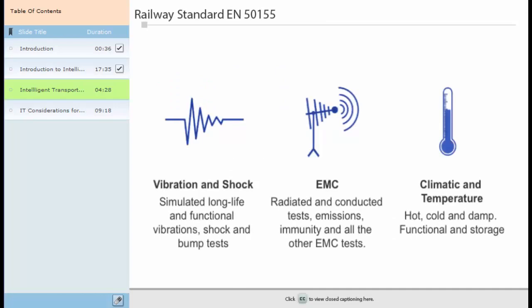The railway standard EN 50155 applies to electronic control, regulation and protection devices on board rail vehicles that are associated with the vehicle's accumulator battery, a low voltage power source with or without a direct connection to the contact system, for example a transformer, potentiometer device or auxiliary supply. This standard covers the conditions of operation, design, construction and testing of electronic equipment, as well as basic hardware and software requirements considered necessary for competent, reliable equipment.